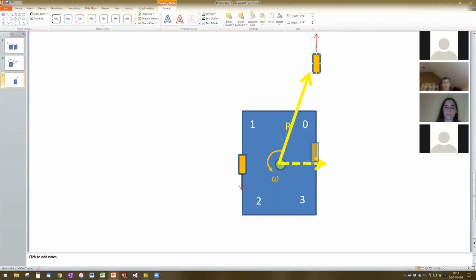As we move the wheel up and down, we don't change this distance at all. Whereas if we move it out, we are changing this perpendicular distance, this distance where you get a 90-degree angle between the velocity vector and the radius. That one does change, and so we do have an effect on how fast you're rotating about the center of the robot. Does that make sense? Okay, awesome.